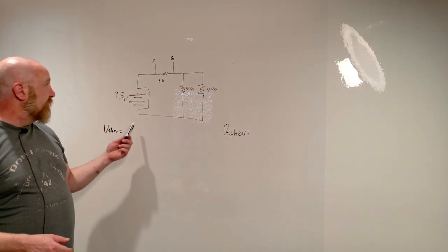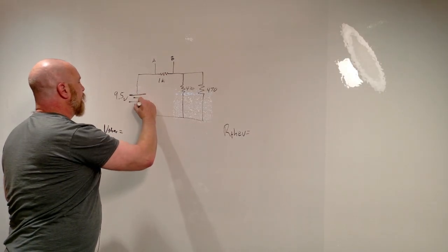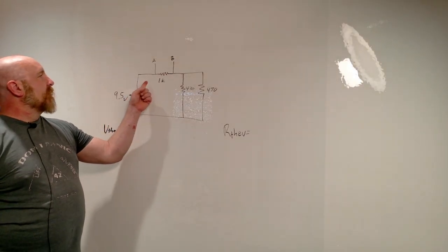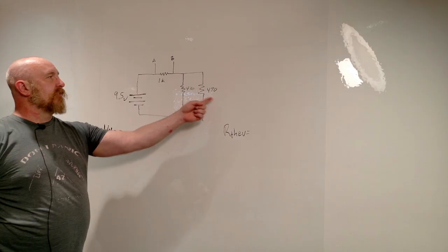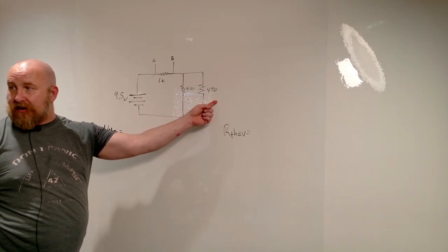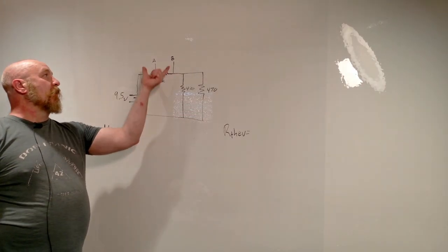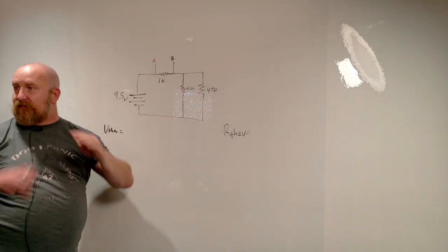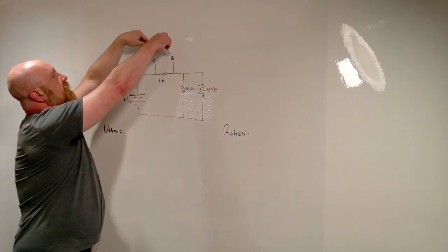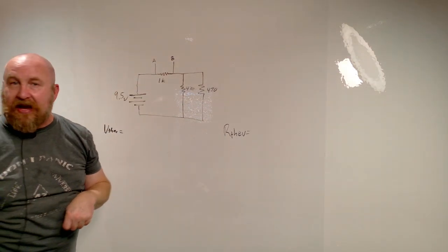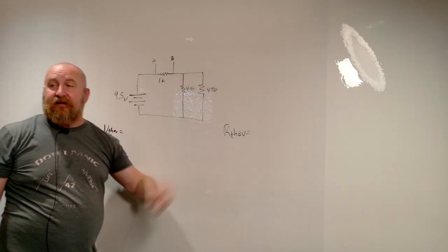And so let me draw this. We have essentially a 1000 ohm resistor in series with two 470 ohm resistors that are in parallel with one another, and then returning back to this. And we are going to do our measurements from points A and B, this black box. So we're going to be touching our voltmeter and our ohm meter to those 2 points around that resistor. So we're going to calculate RThev and VThev from that perspective.